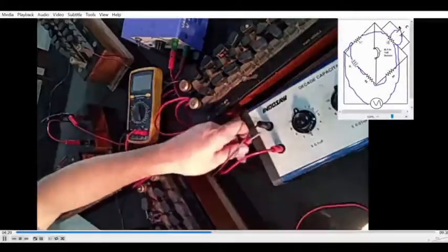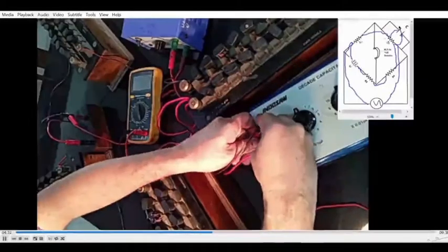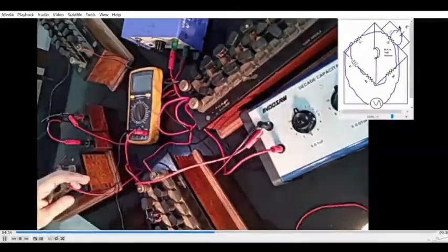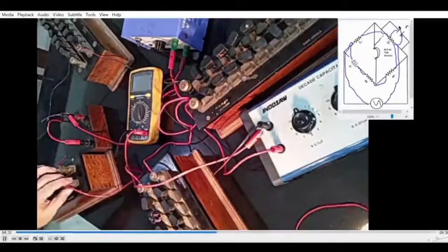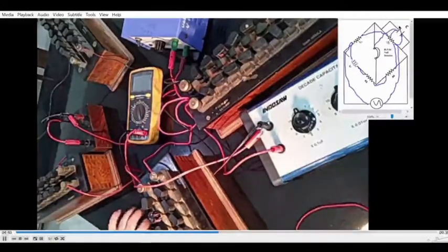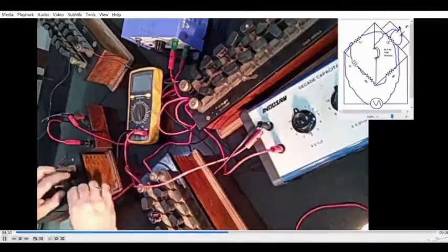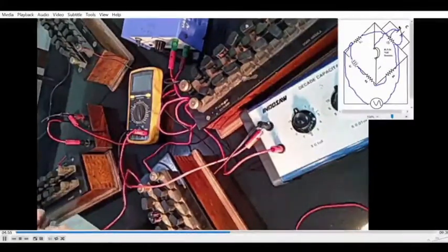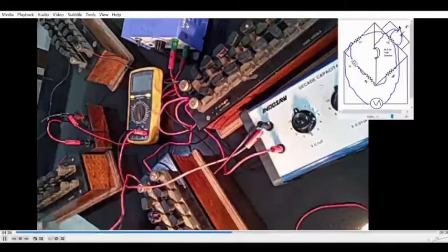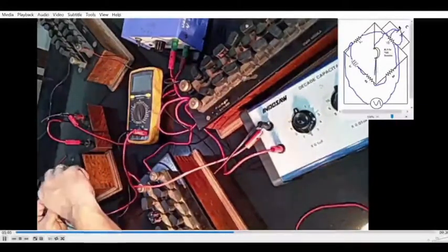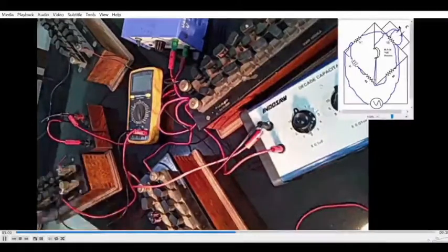So rather than unscrewing that, I have a banana plug, so I am plugging into the capacitance terminal, which is commonly connected with the R1. The second one will go to the R3 and R4 common. So I will unscrew the R3 terminal and connect it here. So this is the end of the circuit, and now I should move towards how to take a reading.